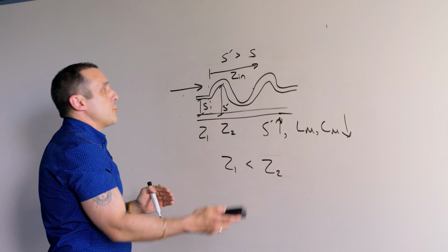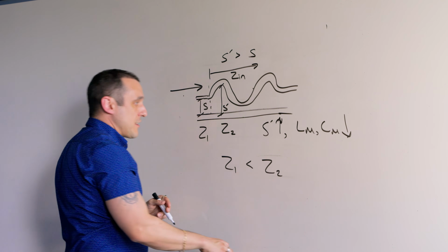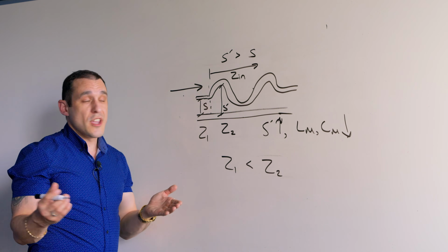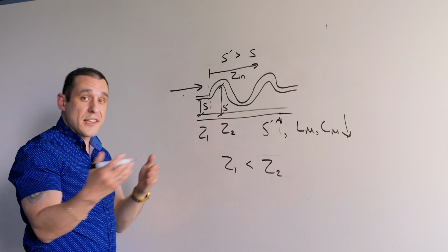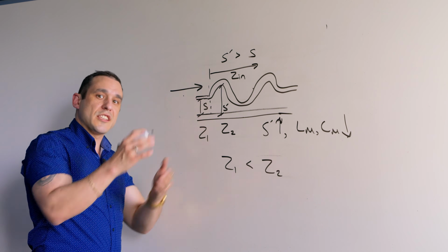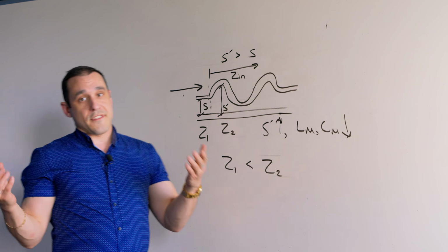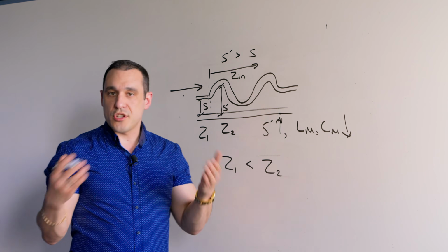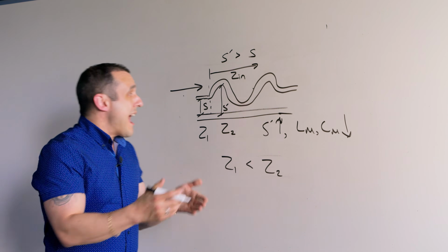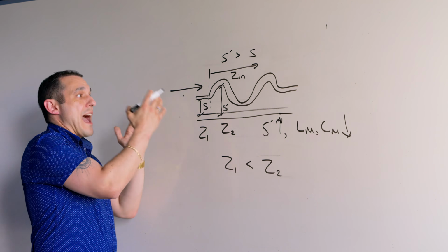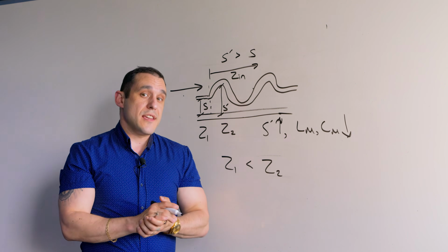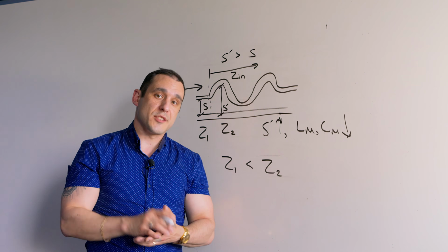So that's why we want to limit the length of these length tuning sections as much as we can, or we want to limit their usage. It's because they basically create losses in your signal that you're trying to transmit along the differential pair. So now we have to ask, what is the frequency range where this matters? How much of the signal does it actually destroy? How much of that common mode noise actually gets converted into differential mode noise? For that, we can use simulations and calculate the mixed mode S parameters.